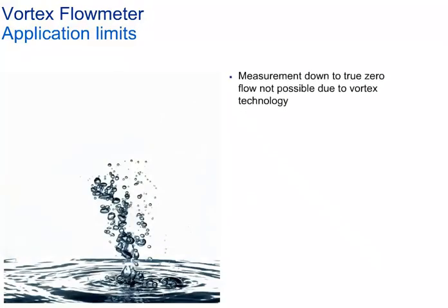Now that you've learned how this measuring principle works, you can understand why flow meters of this type cannot start working from zero, in contrast to electromagnetic or Coriolis mass flow meters, for example. A specific flow velocity is required to build up the Kármán vortex street and to reach the linear range. As a result, a low flow cutoff must always be taken into account. The bluff body constantly causes a pressure loss, which, in the worst case, may cause a cavitation in the pipeline. This cavitation is highly destructive and must be avoided by providing sufficient static overpressure in the pipeline.